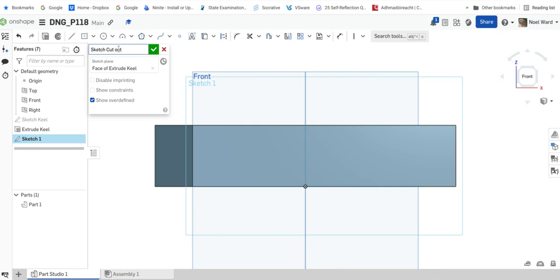So they have to be cut out of the, so it's a sketch of the cutouts. Keep that open. Go up to your rectangle here, go corner rectangle, and just on that line there, draw a rectangle anywhere. And the same to draw a rectangle anywhere there, so long as it's touching the top of it and any size. And I'll hit escape just to get out of that.